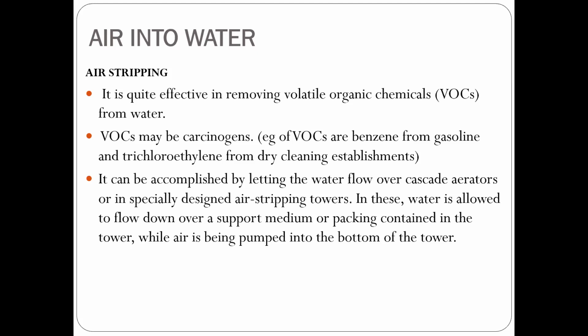So air stripping, whenever this process is carried out, can be accomplished by letting water flow over cascade aerators or in specially designed air stripping towers. Water is allowed to flow down over a support medium or packing, as we have seen in the trickling bed method.